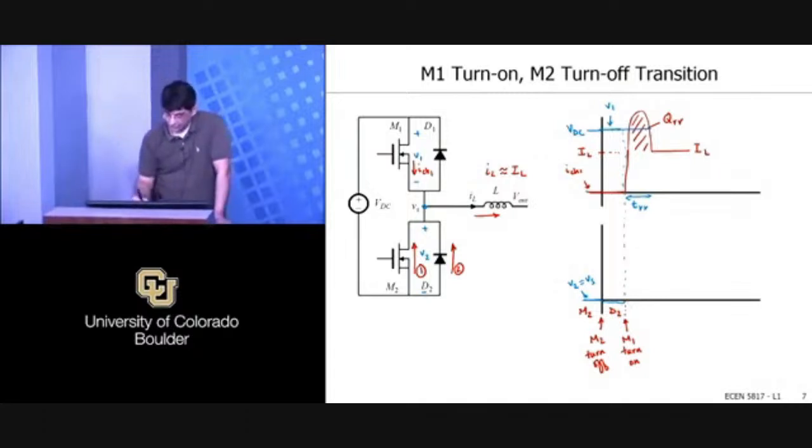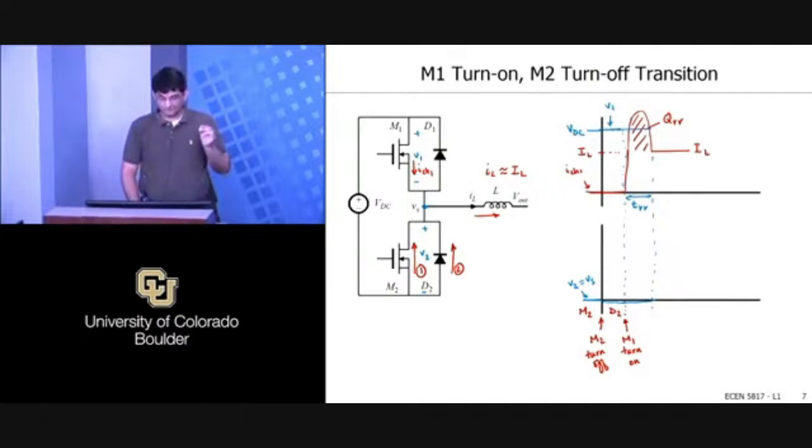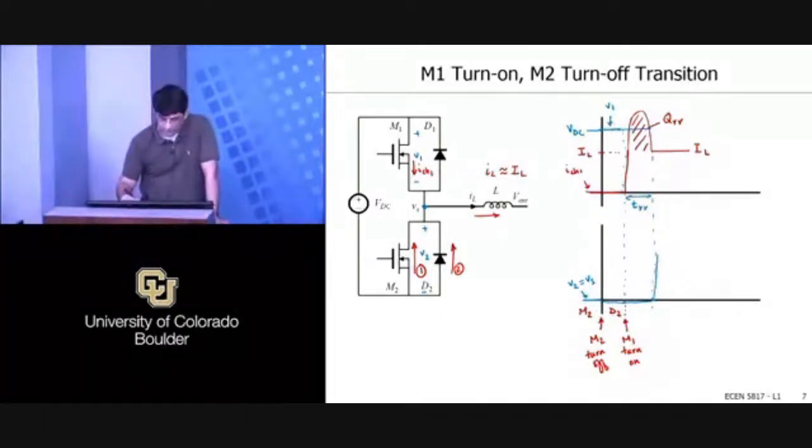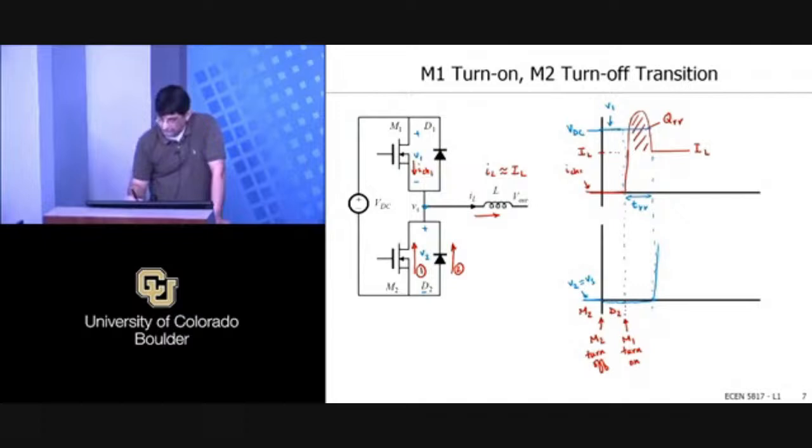So throughout this period we have essentially the diode conducting, and then the diode voltage can go up. And what I'm going to make an assumption for this is that it's a snappy diode. What a snappy diode basically means is that once all the charge is removed, it just snaps back up and it blocks voltage immediately, right? So in the snappy diode, the voltage will then just sort of quickly come up to the VDC level like that, and soften that corner.